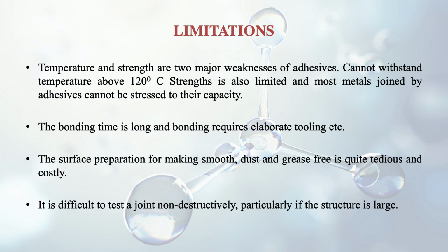And it is difficult to test a joint non-destructively. If you want to test an adhesive joint, then it cannot be done without destroying it or damaging it, especially in the case of a large structure. And then the reliability of the joint is always low in service.